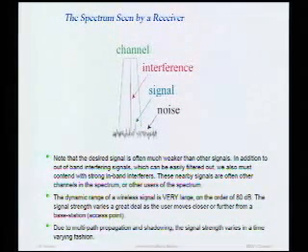In a wireless system, for instance, we have multipath propagation. Multipath propagation means that if I'm communicating with, let's say, the base station, which is at the end of the room, there are many paths between me and the base station. There's a direct line of sight path, there's a path that would reflect off of the roof, there's a path that would reflect off the ground, there's a path that reflects off that window there, and so on and so forth. And so I'm not receiving just one signal, I'm receiving an ensemble of signals.